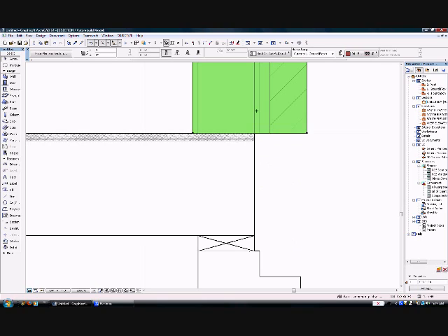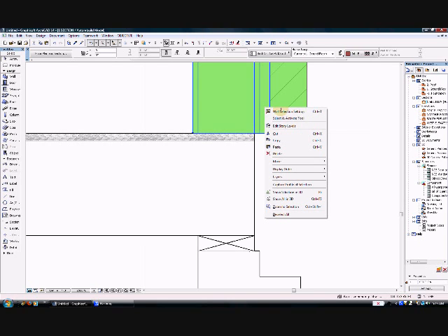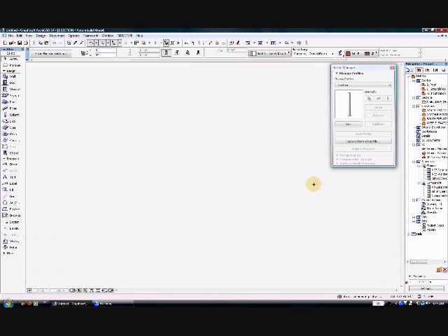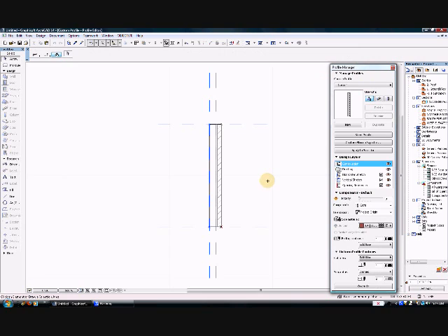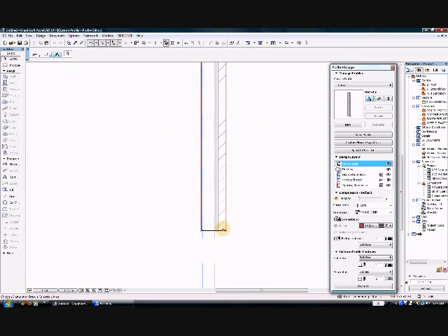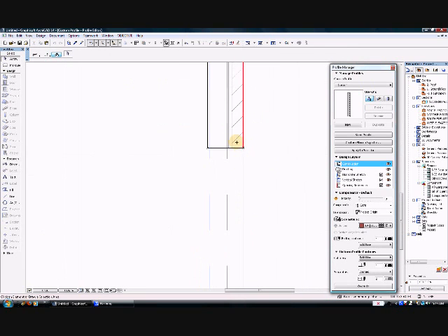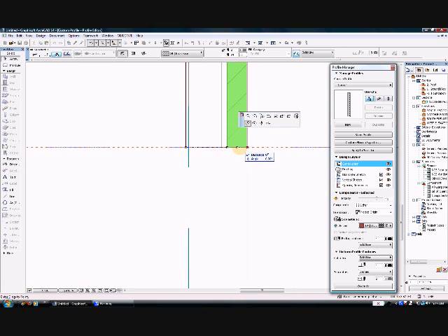So we're going to bring down the brick veneer, the air cavity, as well as the exterior sheathing. So let's right click on it, go to the Capture Profile selection, just like we did with the foundation wall. It'll open the Profile Manager. Now we've taken a composite and we're going to turn it into a complex profile. We'll select the brick veneer fill and use the Offset Edge button in the pet palette and drop it down. Type 14 inches, enter.